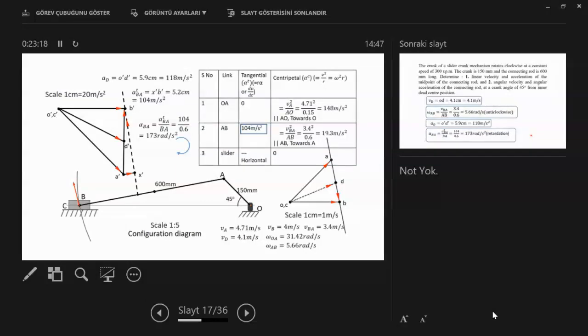Okay, this is the graph here, the vector polygon regarding the acceleration. And I said we know the acceleration of the point A. This consists of only normal components, tangential is 0 because the tangential speed is constant. And then we know the relative acceleration of A relative to B, the normal component, because it must be along this line. I can calculate the magnitude like this here.